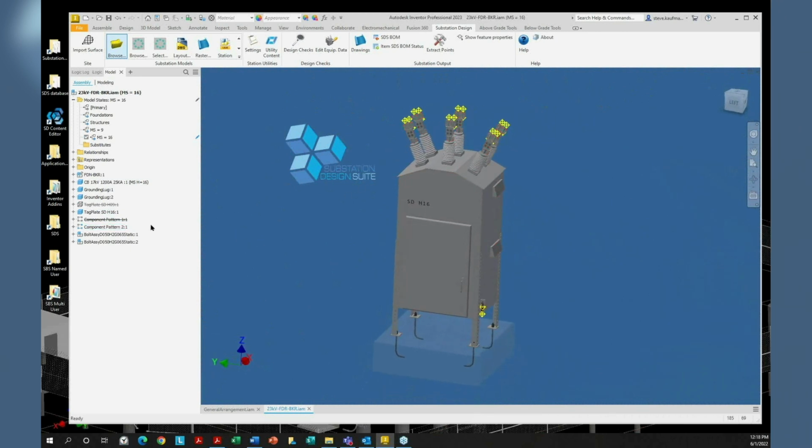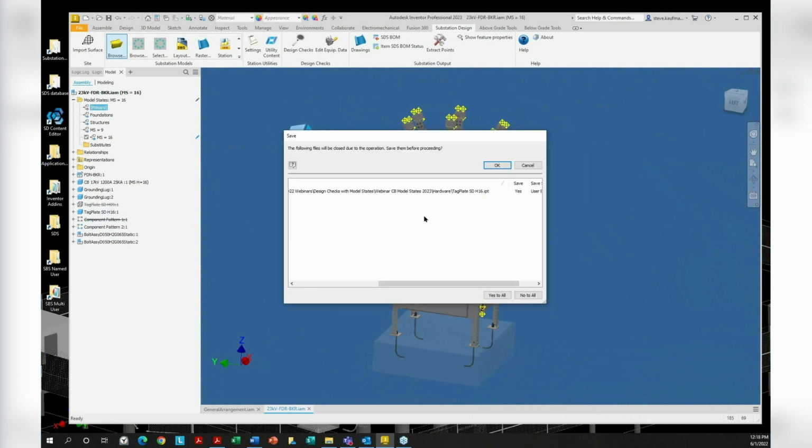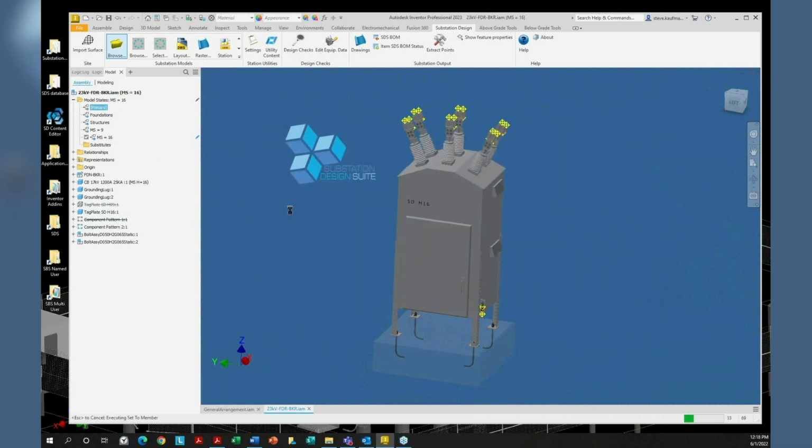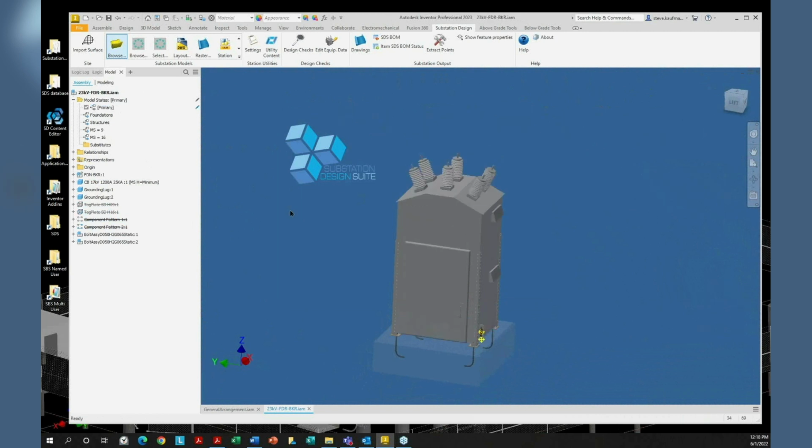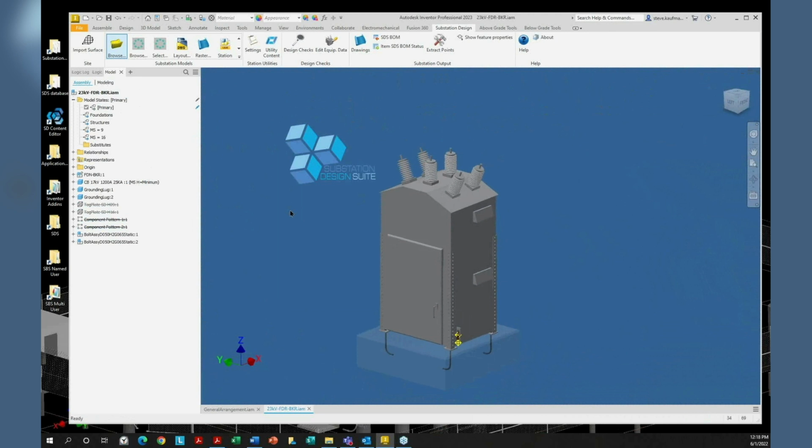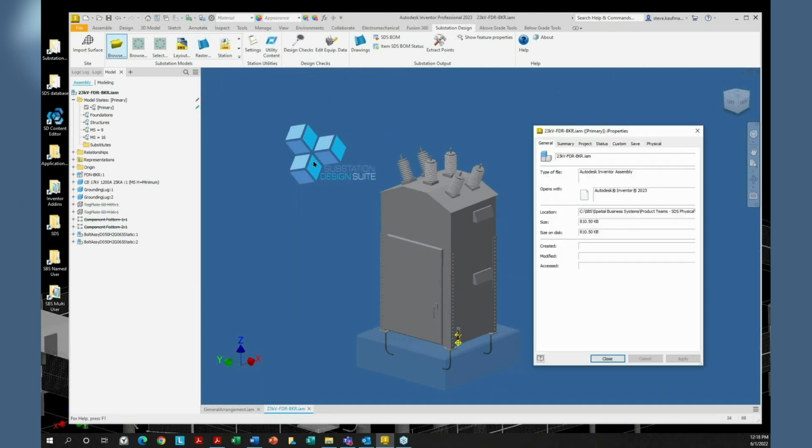I instead added the fittings to my component. So when I have all the fittings turned on, I'm going to have twice as many fittings, twice as much hardware, but it doesn't matter because I'm running it from model states. If I come into primary, I set up the primary model state to have no fittings and to sit at its lowest level. So it's clear that this is not a dedicated model state.